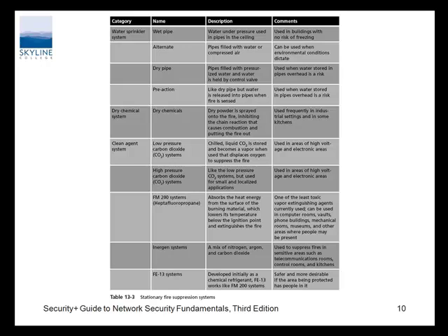In those generator rooms, they had CO2. You didn't want to be in there if something happened because of the CO2 suppressant. Actually, when I was on the gas turbine ship, we had halon in all of the gas turbine compartments, which was one that you didn't have to remove, but you couldn't put any new ones in. It was one that if it went off, it put out just about any class of fire, and it didn't kill the people straight away like CO2 does. If you don't care about the environment, it's about the best one. Yeah, except you can't buy it anymore.